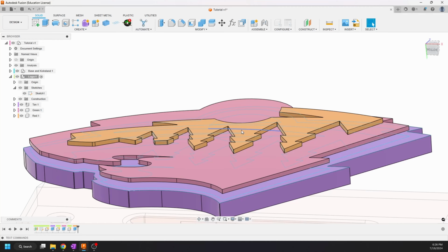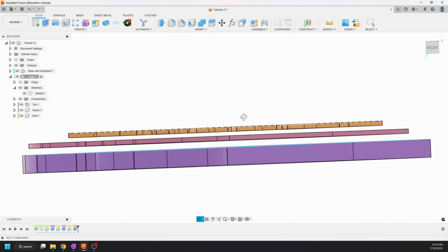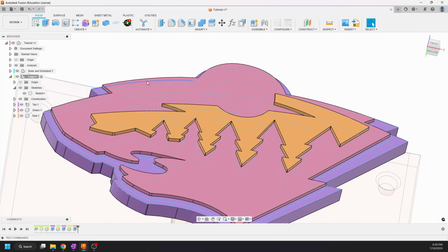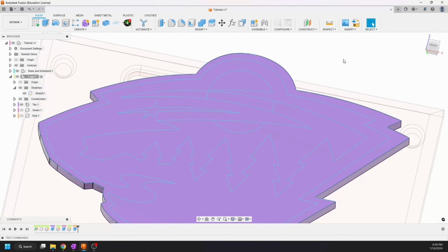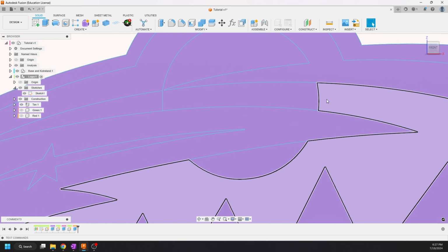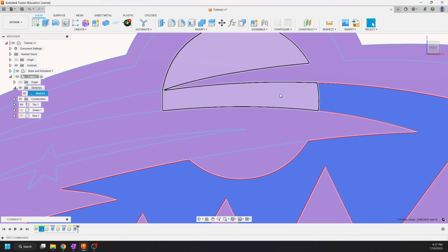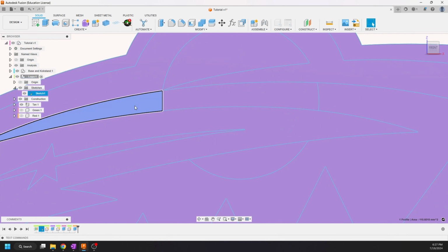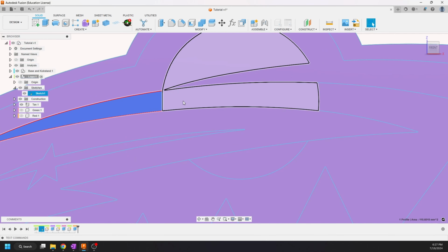For the sun, I am going to... This is another thing. So let's go back over to this. Actually, let's hide these two, and let's look directly at this SVG. So this sun is a cutout of the red portion, which means if you extrude this like we did, and then you extrude this, which I'm actually seeing an error, which we'll go back and fix. We forgot to extrude this part of the red, but again, parametric modeling, very easy to fix.